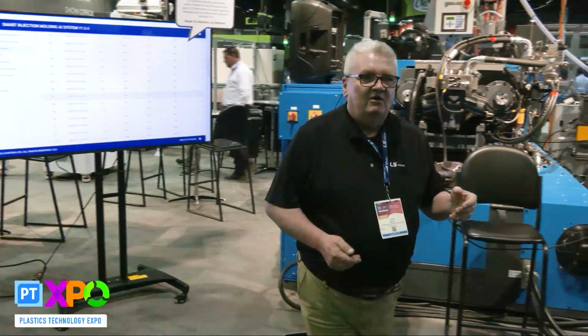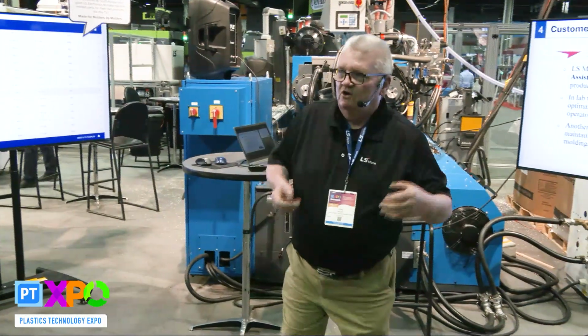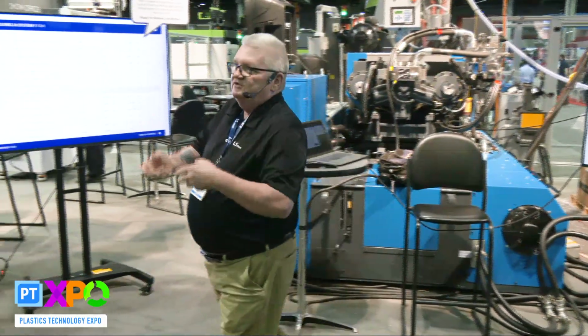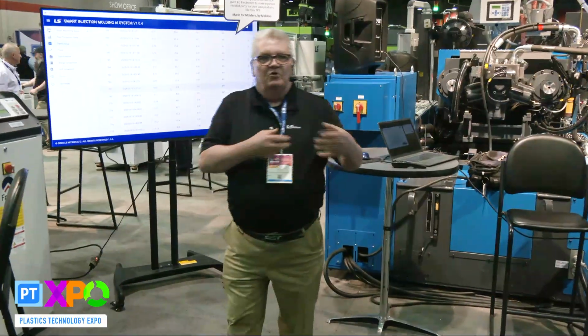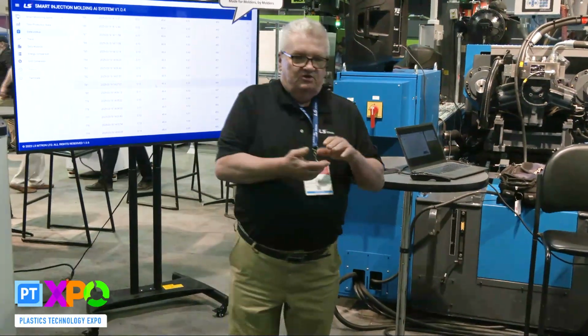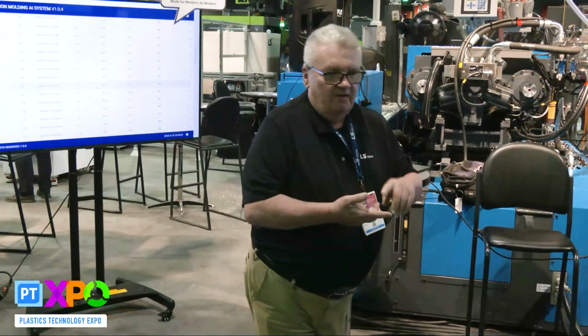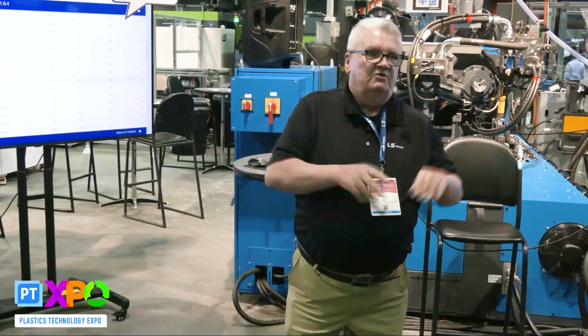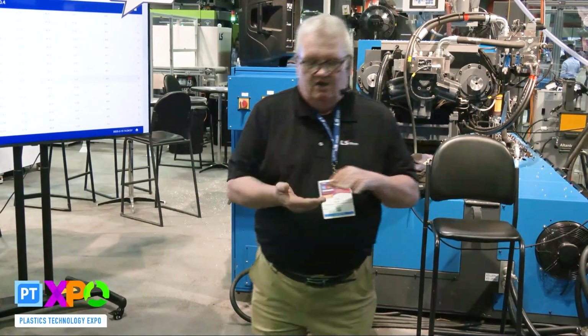With AI, it will give you the smart weight control. So it will add shot or take shot away in order to maintain a good part. So with the AI coupled with the monitoring data with our upper and lower control limits, we can have a process that's stable and a process that's repeatable.